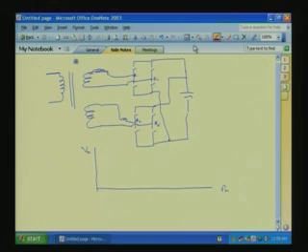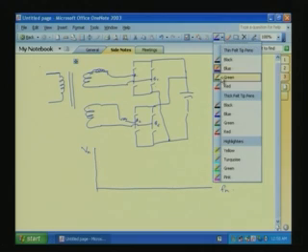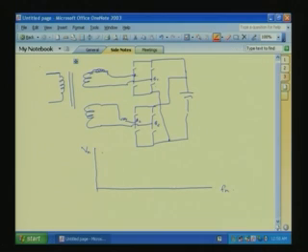So, you have the fundamental here, then all the harmonics at Fc and its sidebands, that is this one, this is Fc and its sidebands, also at 3Fc and its sidebands.